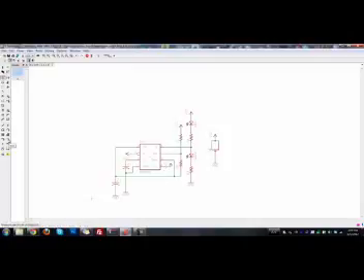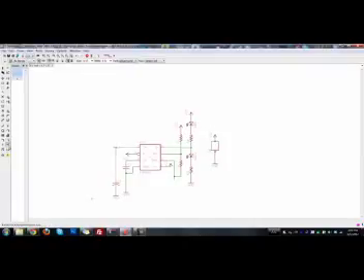So let's go ahead and delete this wire. So we want to connect this to this. So what I'm going to do is just make little connectors here and there. And then we're going to choose to label each of these nets. By giving them the same name, it will automatically virtually connect them. So you saw before, the net names are like $9, for example. So we're going to add this label to that so that it's easy for us to keep track of.